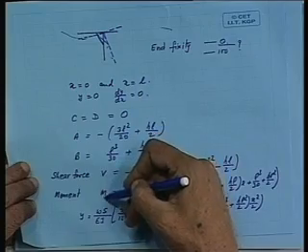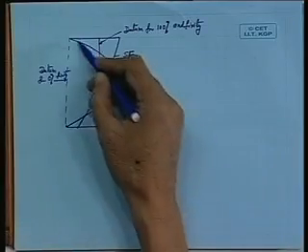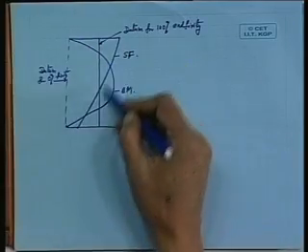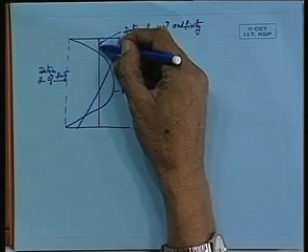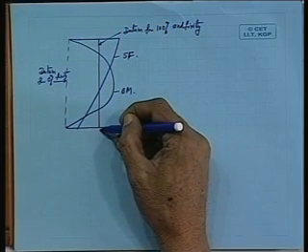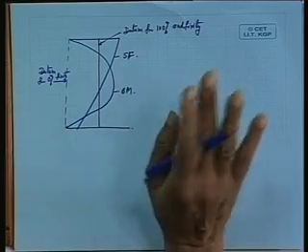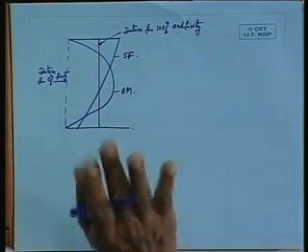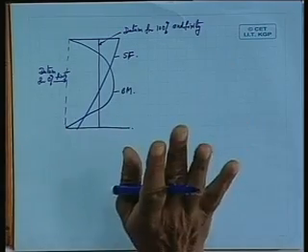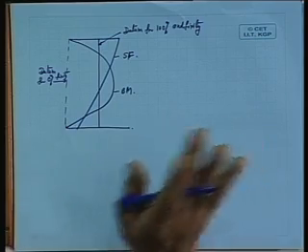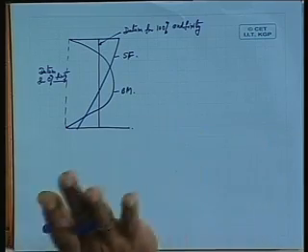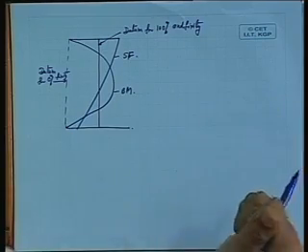See, according to these expressions, I have tried to plot shear force and bending moment, which goes like this, with respect to this particular datum, which is 100% fixity I have considered. Now, if I assume that the end fixities are 0%, that implies that the two ends are not capable of sustaining any bending moment.